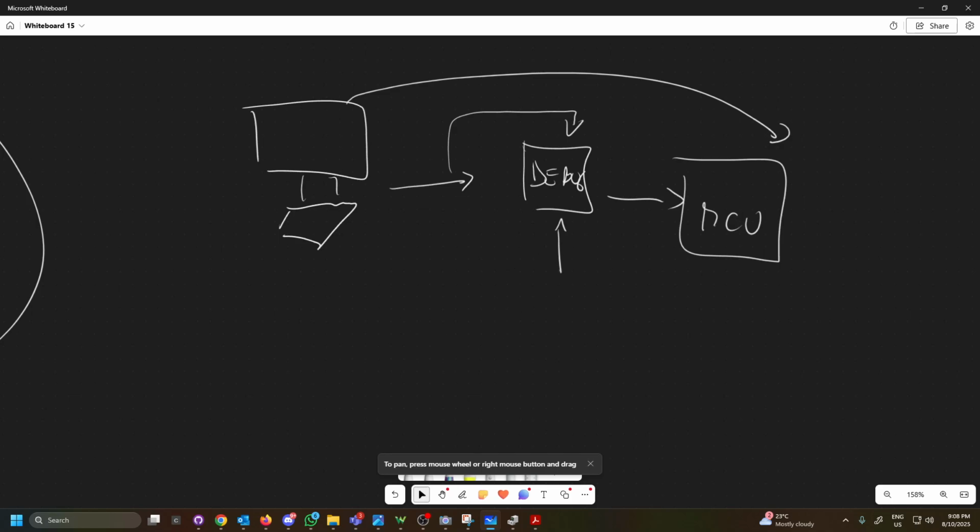So in some other cases, you will use a specific box that would have inside a debugging interface to program the actual target microcontroller. In this case, in this development board, everything is integrated. And that's why I showed you that we had a micro on the top and on the bottom side of the board. So everything is integrated on the same board. So this debugging capability, we have it already on board. And all we need is just a USB cable to connect to the actual computer.